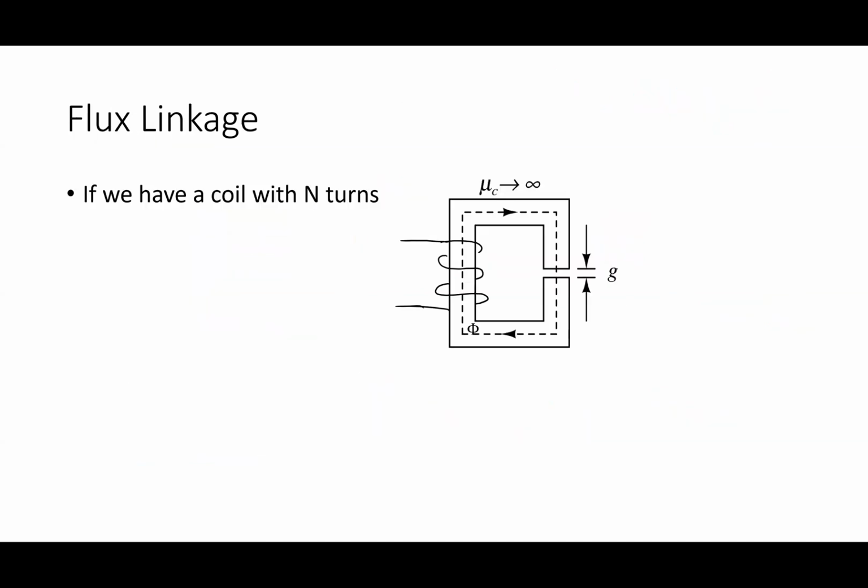Now, a really important concept is if I have something like this. First of all, it's an inductor, but it has 2 coils, maybe that's hard to tell. It just looks like 2 crappy windings. This one has 2 coils, which means it's a transformer. Now, what if I took the 2 coils and connected them in series? Then it's back to just a single inductor, which would be one inductor plus the other. If I have inductors in series, they sum.